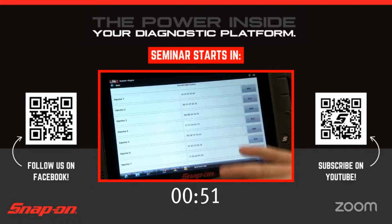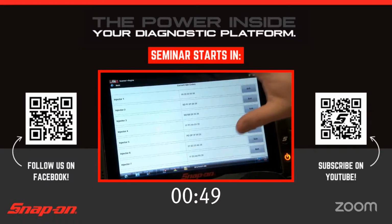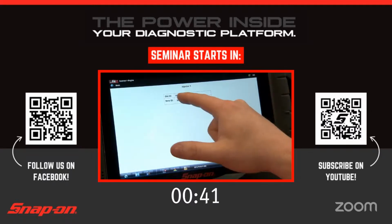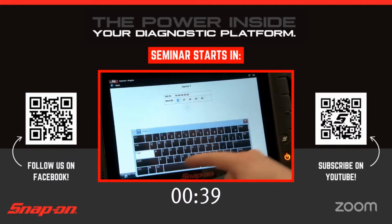It's going to display all of the codes that are already coded to the computer. And we see there, injector 1 is all 0, so we need to program that one in. So we'll just hit edit, and we'll program it in.